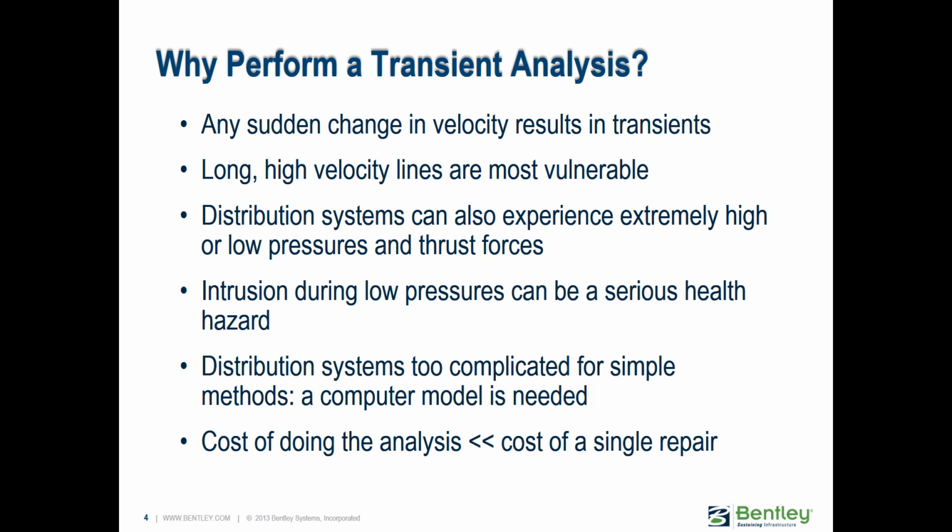We also need to check for the downsurge to make sure that we don't have pressures below zero that could suck contaminants into the pipes. That could be a health hazard. It could also buckle the joints, and you can have some physical damage from that. If the pressure drops too low, you can also have vapor form, which we'll talk about a little bit later, and that can subsequently cause another upsurge, a water hammer effect, which could cause even worse problems.